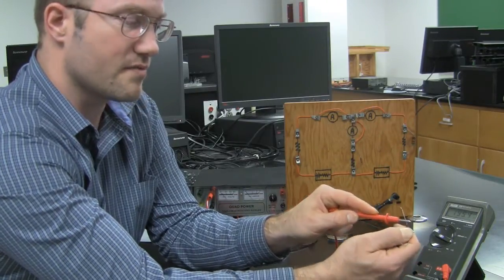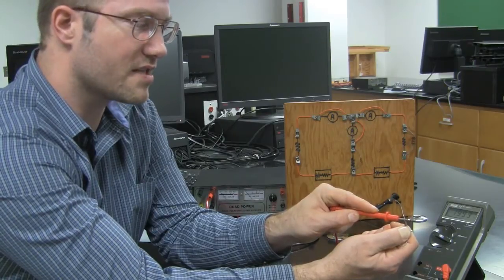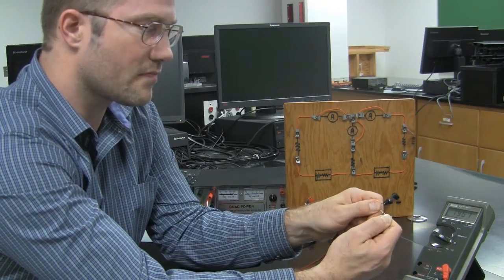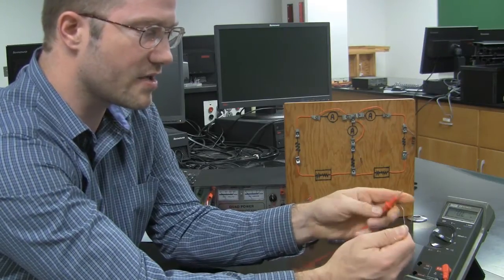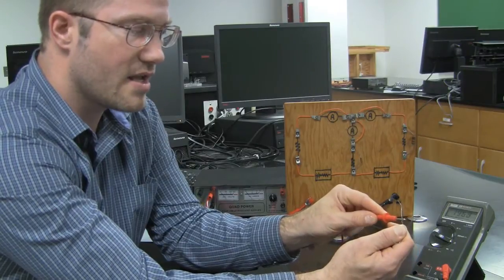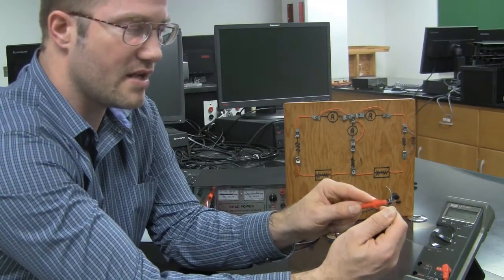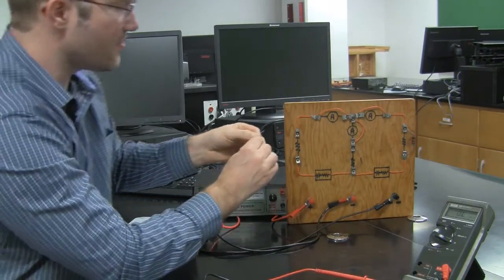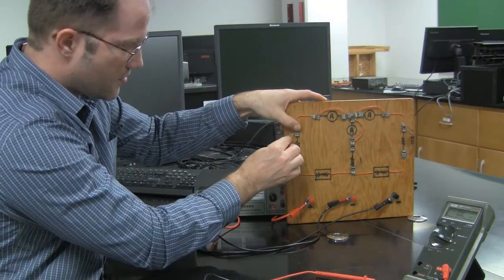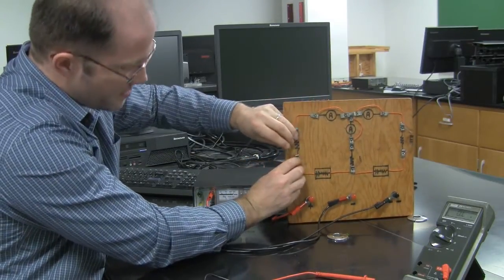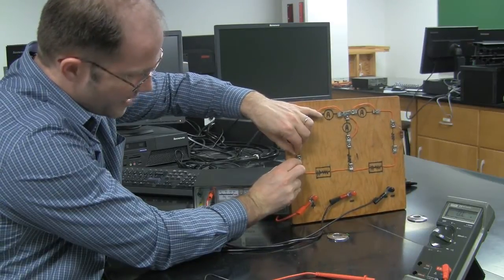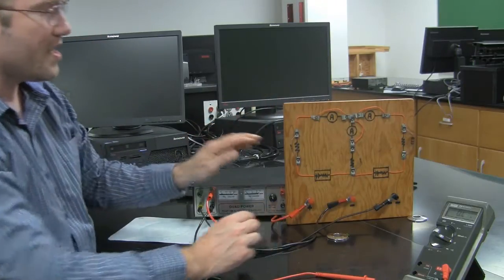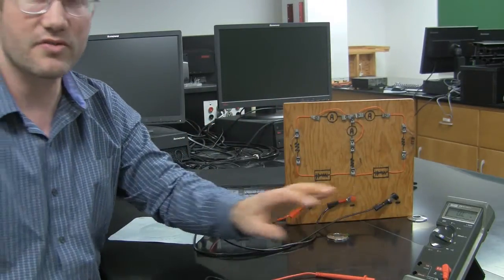So I'm going to read this resistor. I'm measuring across it: 1,993 ohms. I want to hold the resistor with one hand and the probe, and then attach the other probe right here. So I've read my resistance. Now I can put it back into the circuit and read the other two resistors, but I'll let you do that. Your resistors will have different values from my resistors. They're not the same. All right, so now I've measured the three resistances.